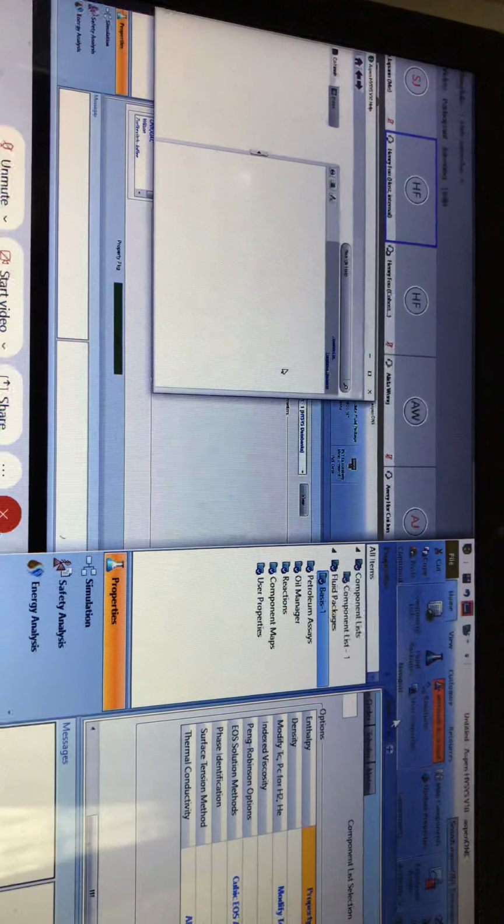If the question never specified what type of fluid package to use, then you can select Method Assistant on top. Under the Home ribbon, you can see we have one option called Method Assistant, and you can click on it. Basically, it is a help tool to help you search which fluid package is suitable for your system. You just need to answer the questions.